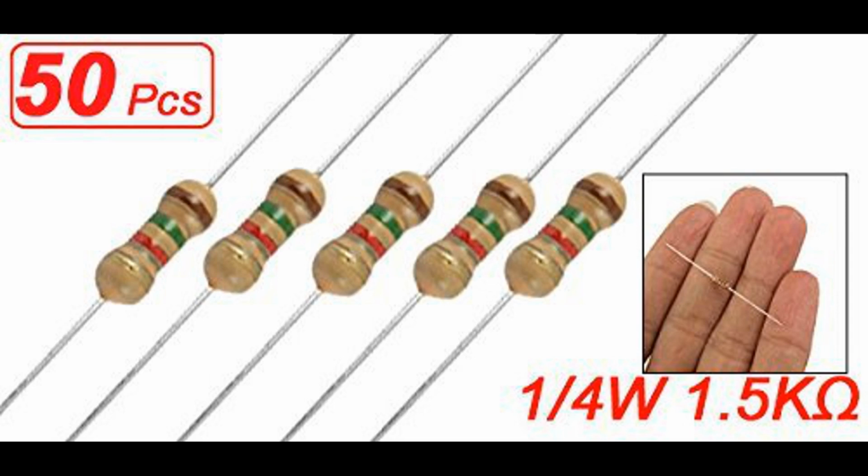Voltage dividers consisting of resistors are commonly used in sensor applications to convert sensor resistance changes into voltage signals that can be read by microcontrollers or measurement circuits. Pulse shaping. In pulse shaping circuits, resistors can be used to control the rise and fall times of square waves and pulse signals. Power scaling.